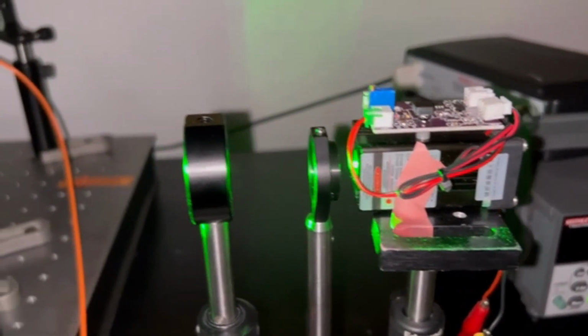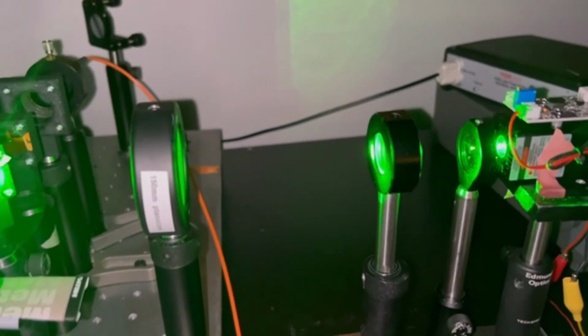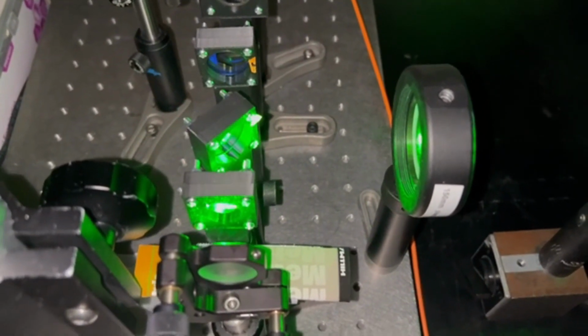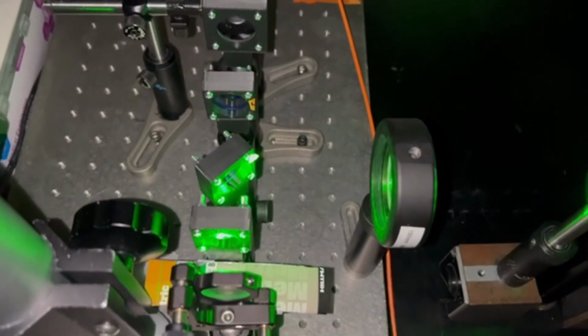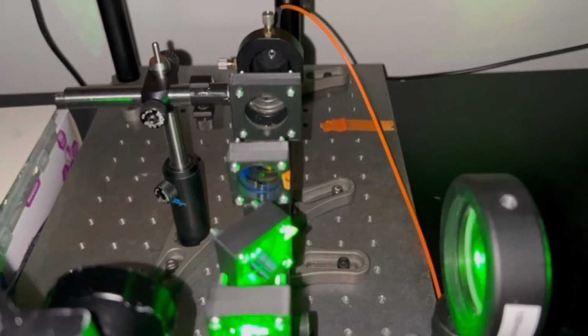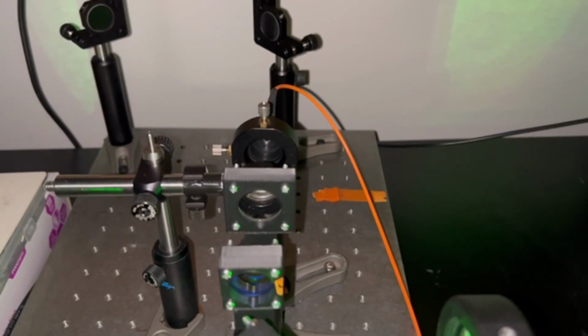After the laser is turned on via user input on the LCD, it is passed through a bandpass filter and then a beam expander setup to clean and enlarge the beam. This beam then hits the 45-degree dichroic mirror and is reflected onto an 18mm focusing lens to create a tight focus on the sample. Any Raman scattering that occurs is recollimated by the focusing lens, passed to the dichroic mirror, then isolated by a long-pass filter.